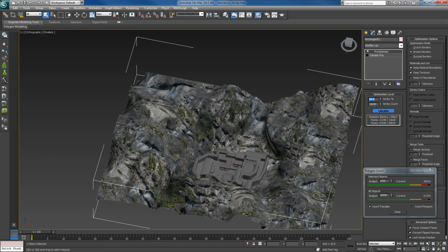I didn't see anything happen. Let's turn it on, off, on, off. Okay, we dropped down by half, and there is absolutely zero resolution loss as to geometry, shape, and form. Nothing changes. The only thing that changes is you see a little bit of sparkle over here. That's not a change in shape and form. That's a change of the smoothing group information on this surface, as 1 combines with 2 when we drop the count by half.